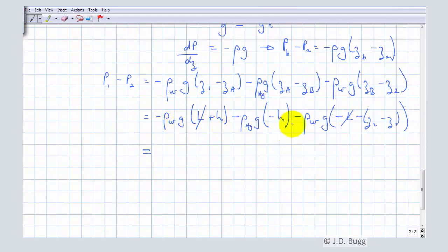So I'm going to combine these two terms together now. So I'll put rho water times G times H times the specific gravity of mercury minus 1. So that is the same as these two terms combined together. So notice negative times negative is positive, and this is mercury. So that's where this positive specific gravity of mercury comes from, because I factored out density of water. And then this term here is minus rho water G H, and that's this, minus 1 here, minus rho water G H.